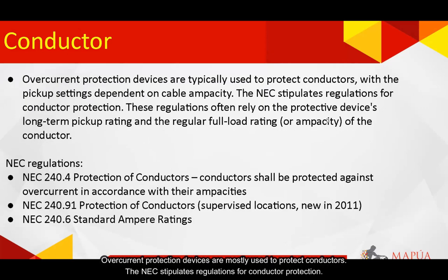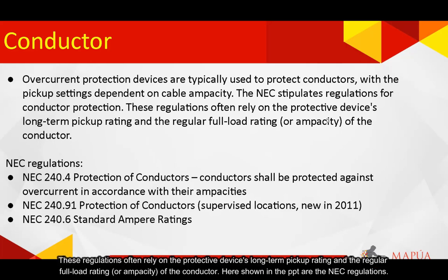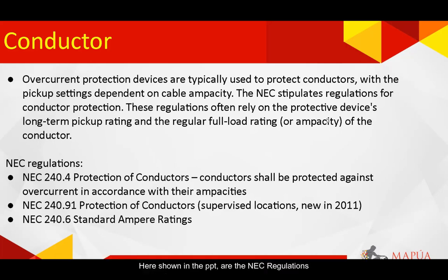Overcurrent protection devices are mostly used to protect conductors. The NEC stipulates regulations for conductor protection. These regulations often rely on the protective device's long-term pickup rating and the regular full load rating or ampacity of the conductor. Here shown in the PPT are the NEC regulations.